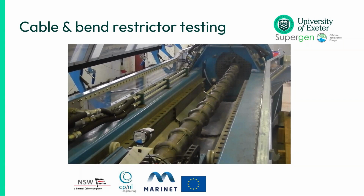And one of the conclusions was that whilst the cable bend restrictor provides some additional integrity to the cable, it still allows it to move. So one of the conclusions was that those cables at the end will have some fretting and some wear inside them, because although you reduce the amount of movement, there still is movement.